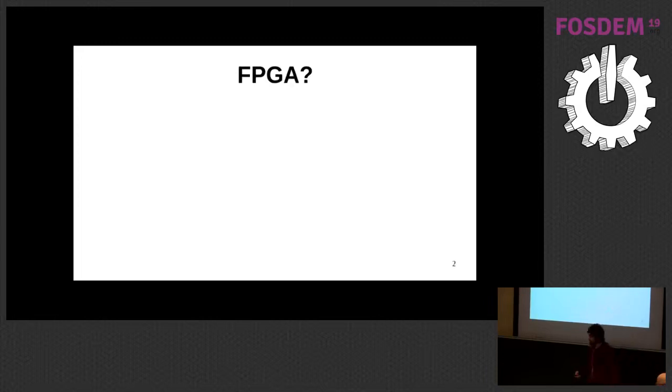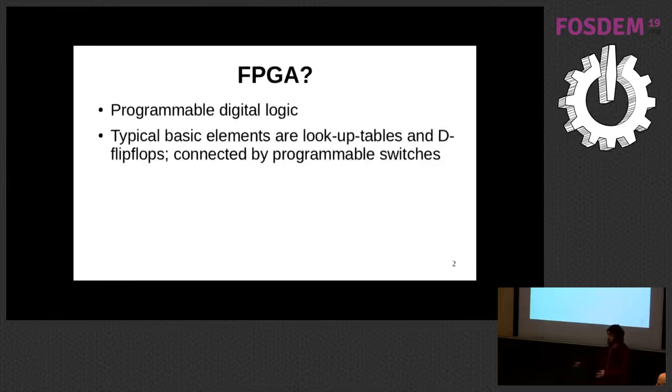Awesome. So just for people that haven't, what is an FPGA, a Field Programmable Gate Array? It's programmable digital logic. If you look inside a modern commercial FPGA, there are two really fundamental elements: a lookup table and a D flip-flop. A lookup table has maybe 4 or 6 inputs and 1 output, and you just tell it what the binary value of the output should be for all possible combinations of inputs. The other fundamental element is a D flip-flop. That's just 1 bit of memory storage, and that's used to build sequential circuits that do more than just combinational logic. And all those elements are connected together by user programmable switches.